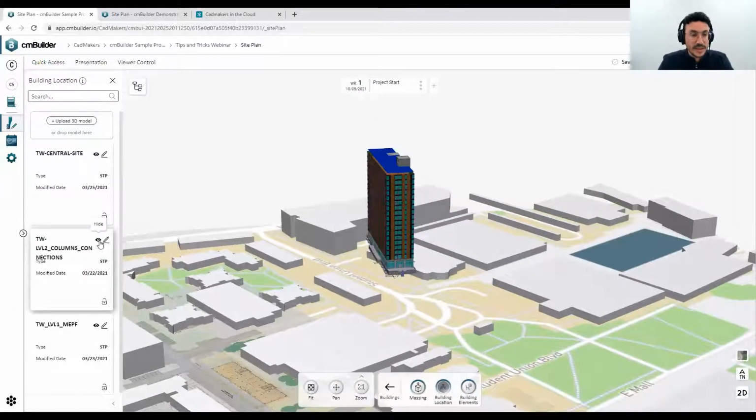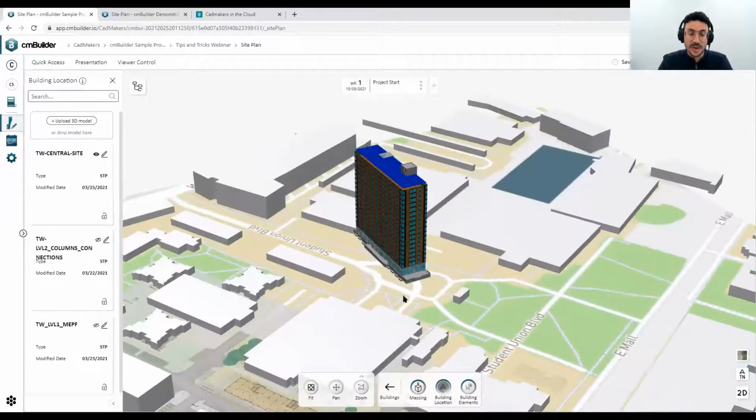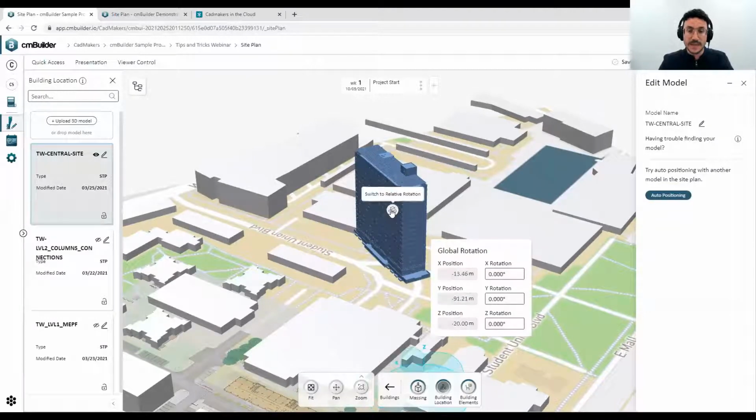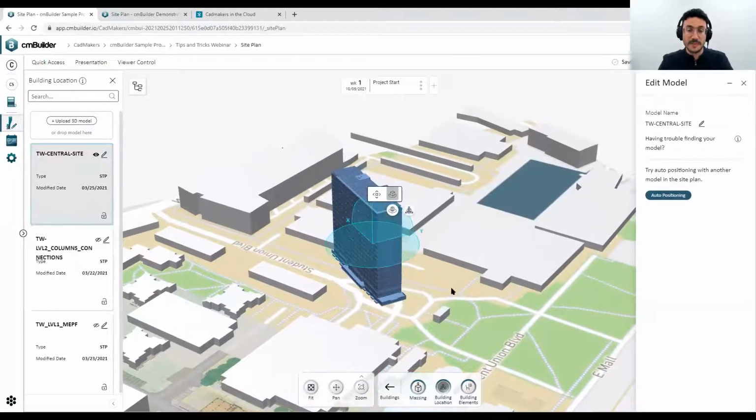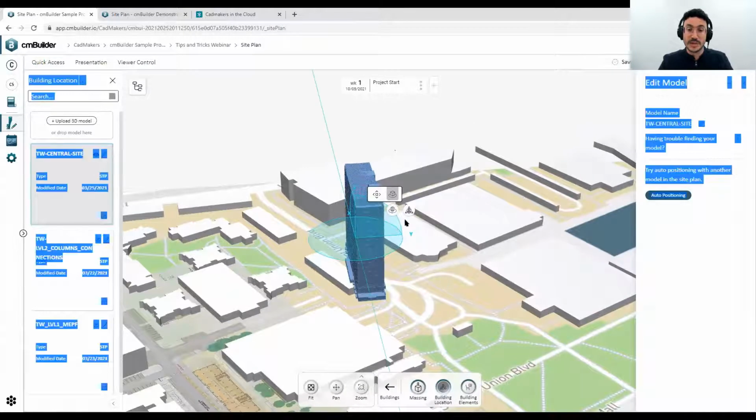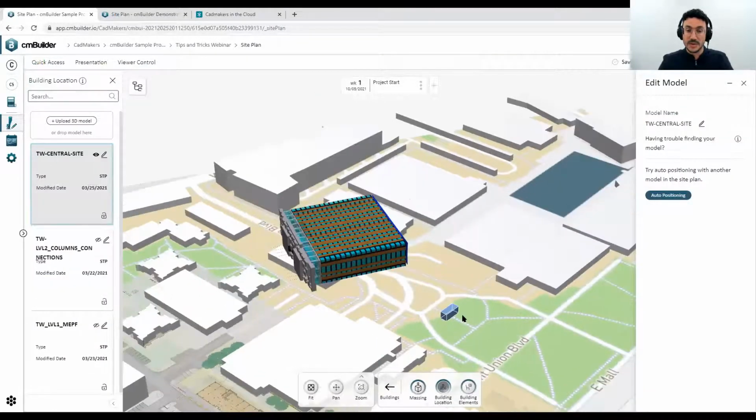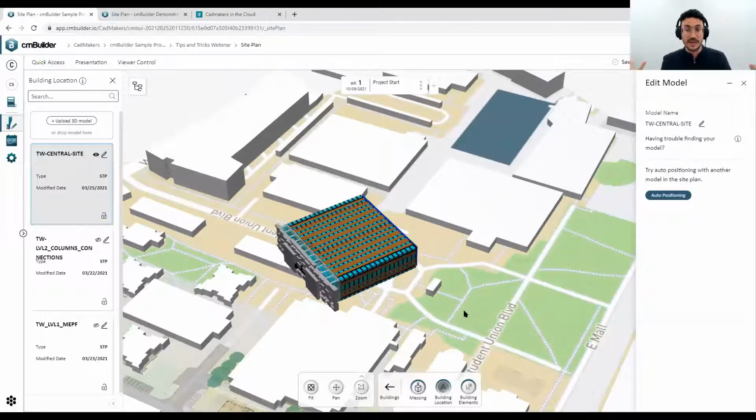So one thing that I think is important for us to mention is that whenever you bring in FBX imports, usually coming from Navisworks, they have their Z reference pointing sideways and the Y reference pointing up. So it's different from when the model comes from Revit, where your Z reference is pointing up, right? So usually, just to showcase how it would look, if a model is coming from Navisworks, the model will look something like this, right? So this is basically how Navisworks imports.